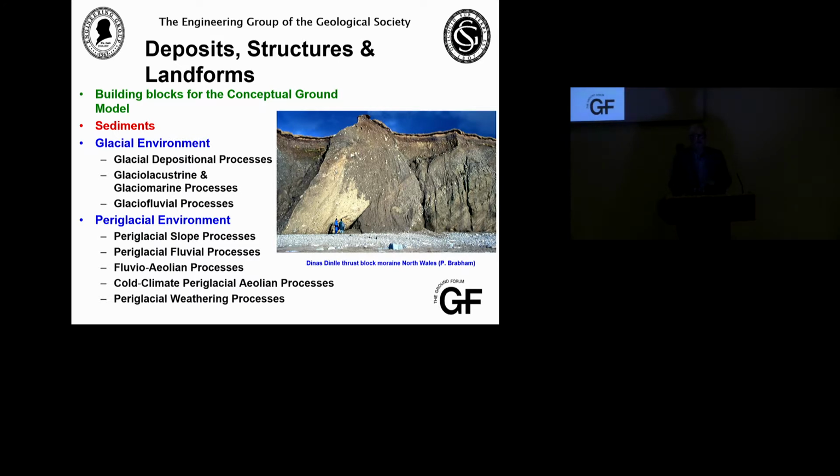There was a lot of dialogue about what terms we could utilise. We actually had quite a considerable argument in the working party. There's a term that is much loved in physical geography called a diamict and a diamicton. And in terms of engineering geology, it's a term that's hated because it doesn't mean anything. And there were some serious discussions and almost shouting about where we could actually get to with this. And my graduates in the audience will know there's one term we don't use, which is the BC term that migrated throughout, the boulder clay term, and how you actually remove this from the literature.